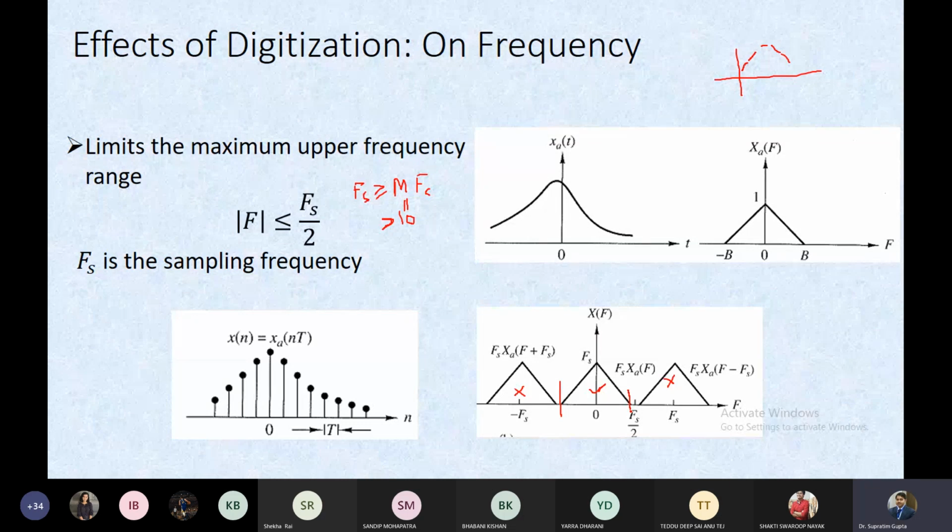All right. So we can take one speech signal and then employ an anti-aliasing filter, which is essentially a low pass filter. Then the output of that low pass filter is fed to the ADC. This is analog in nature, and it has some Fc, the cutoff frequency.